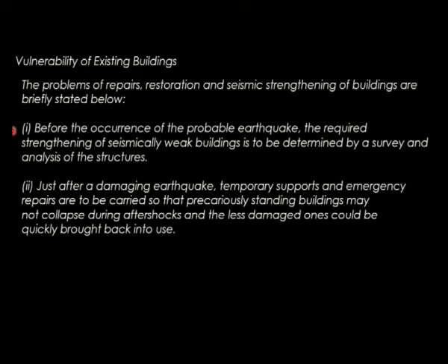Talking about the vulnerability of existing buildings, the problems of repairs, restoration and seismic strengthening of buildings are briefly stated. 1. Before the occurrence of the probable earthquake, the required strengthening of seismically weak buildings is to be determined by survey and analysis of the structures. 2. Just after a damaging earthquake, temporary supports and emergency repairs have to be carried out so that precariously standing buildings may not collapse during aftershocks, and the less damaged ones could be quickly brought back into use.